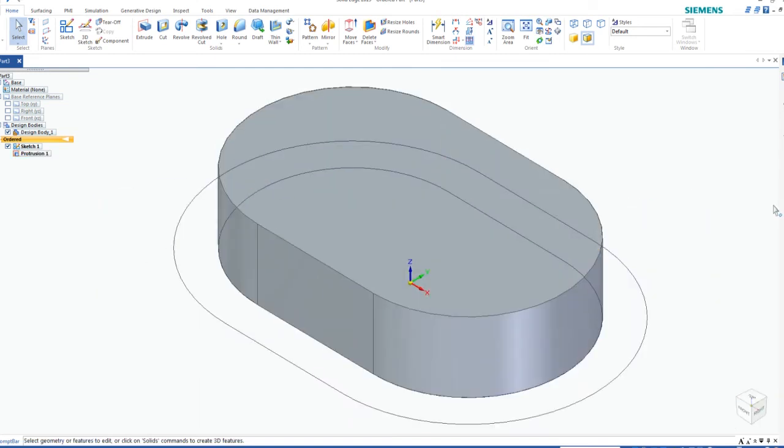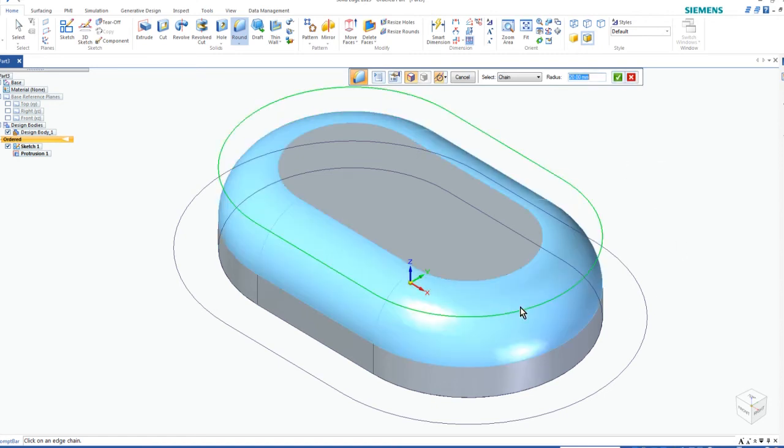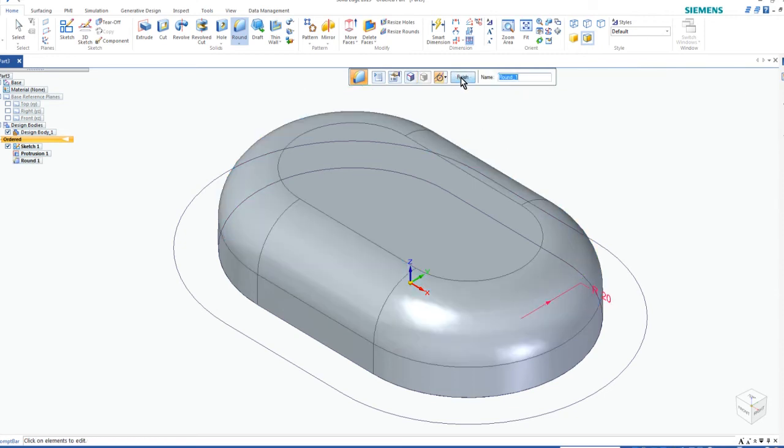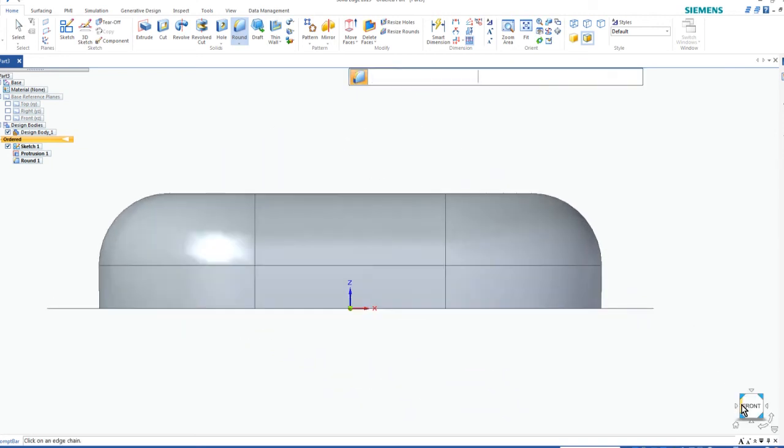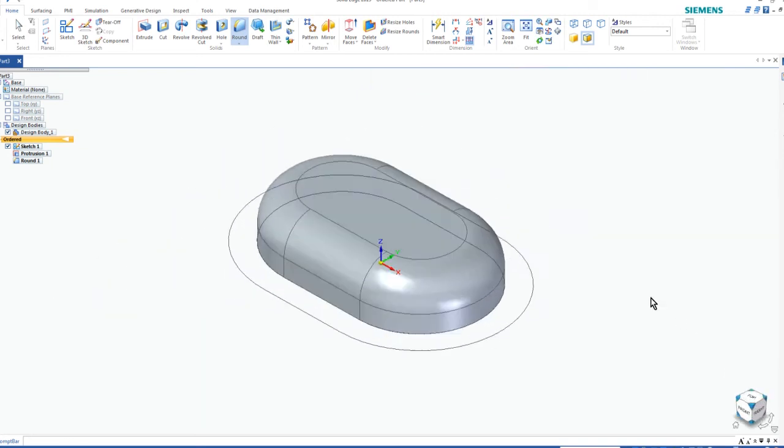It's actually a bowl, and the radius is on the section view, and the outside radius indicates that it's 20 millimeters. So we're going to end up using the round, which is right here. I'm going to click on round. I'm going to type in a radius of 20. I'm going to hit enter. Then I'm going to select that edge, accept it, and hit my preview and finish. So now I have the dome, and if I take a look at it, that's the profile that I want. Okay.